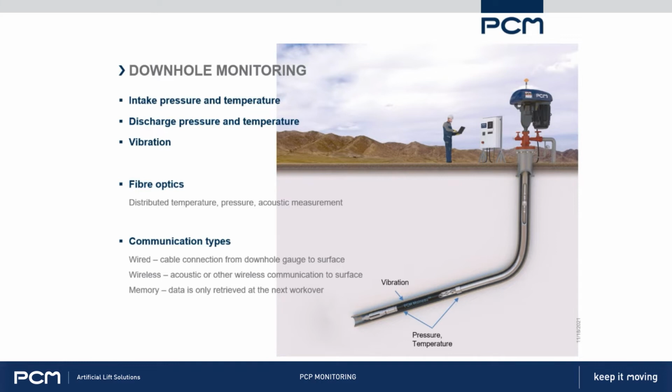There's also memory gauges. Those are good for certain applications, but not for any kind of control, obviously, because you don't get the data until the next workover.